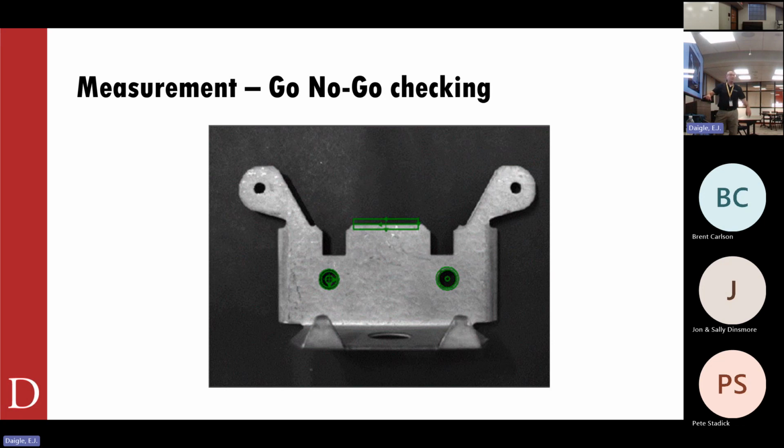Because maybe I find out, hey, this hole on the bottom here on the upright, that hole is extremely important, along with everything else on the flat. Okay, well, then I'll just put in another camera just to read that other hole. So I can just get that other measurement so I know if I'm good or not. Does that make sense?